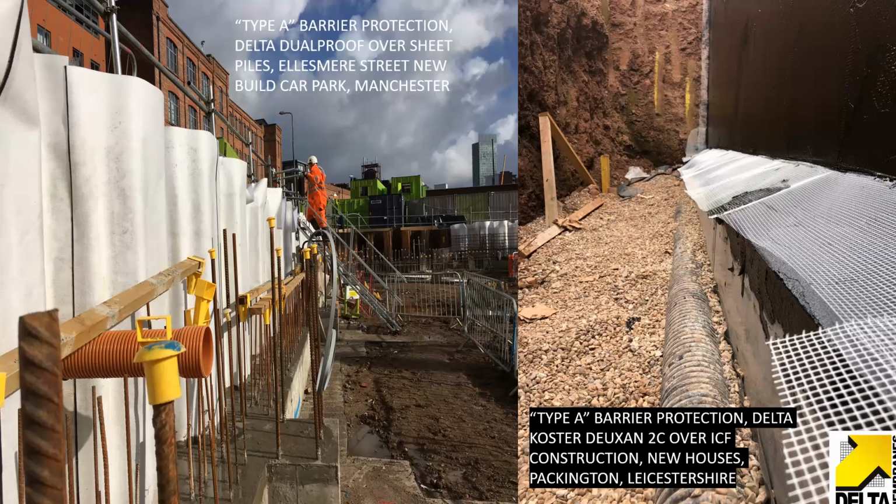So you can see there the reinforcement mesh poking out and the land drain to depressurize the groundwater, which can build up against it. So that's a troweled or post-applied system, if you like, applied after the structure has been done. So these are all type A.